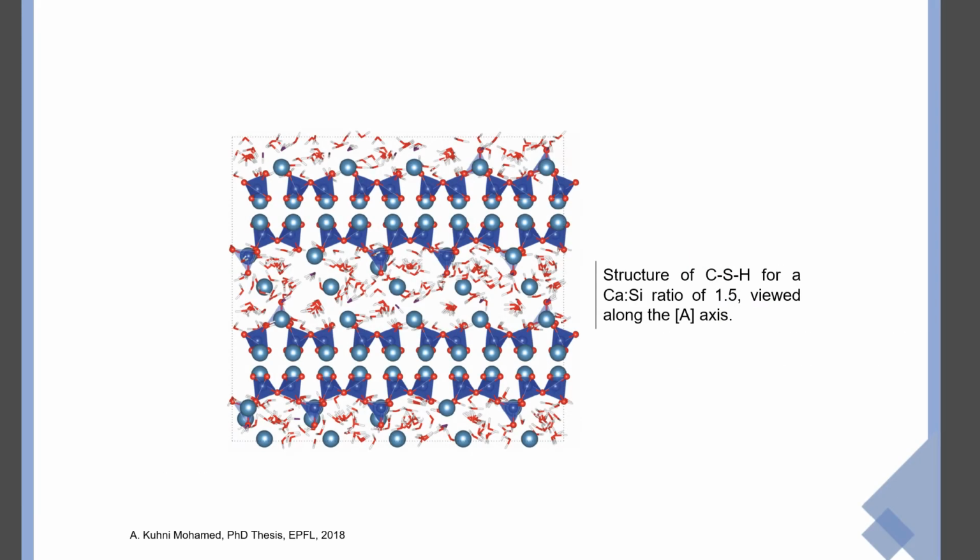The objective of one of our colleagues from ERICA is to model the adsorption of ions and small organic molecules onto the surface of CSH. These ions and small organic molecules can change the morphology of CSH and consequently the properties of the hydration product. By using atomistic simulation, like molecular dynamics with LAMMPS code and metadynamics simulation with PLUMED code, one can adequately simulate the adsorption of these substances.